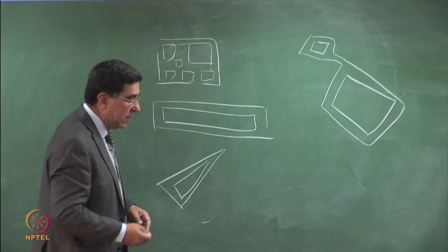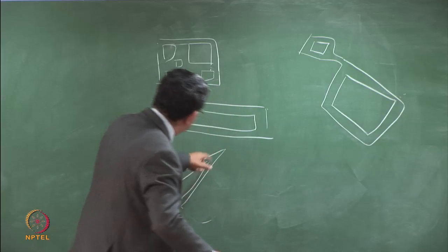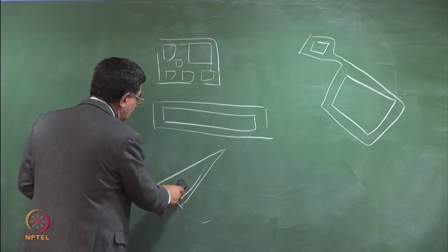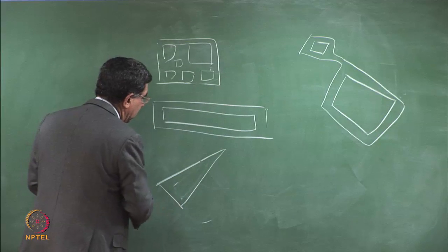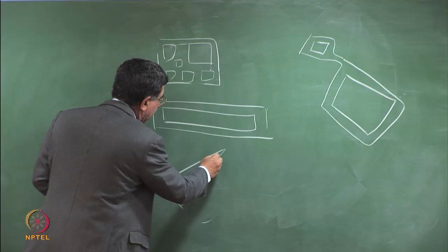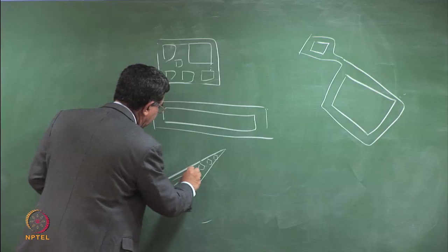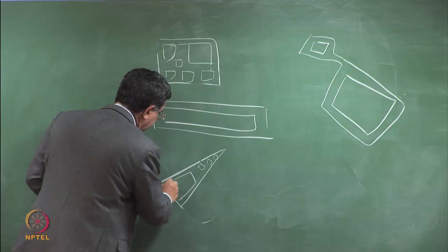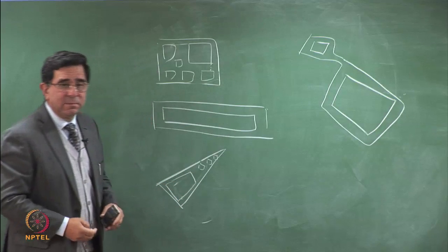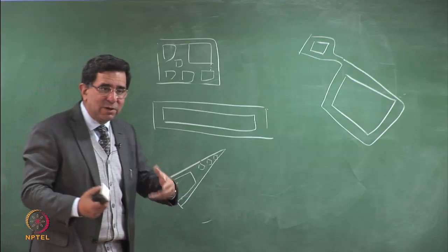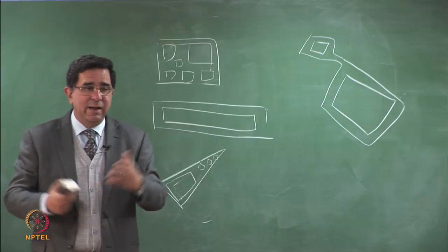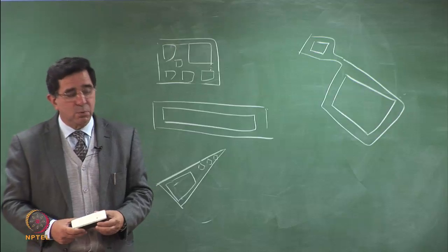In fact, here what we did was, we remember this was hardly any area. So all the pre-processing and the treatment facilities came here because we needed more base width, and the landfill only came here. In the narrower areas, you can put the stuff, it doesn't have to go very high, and you can use that area appropriately.